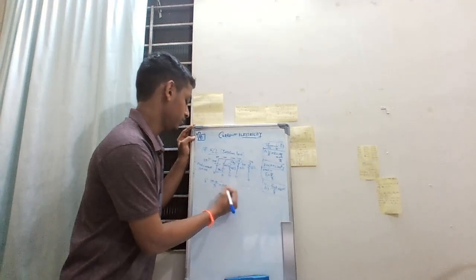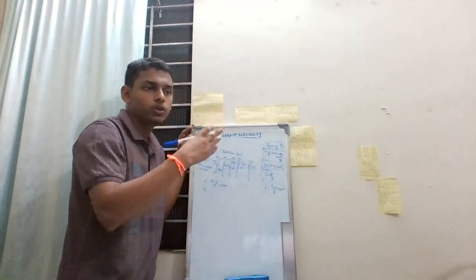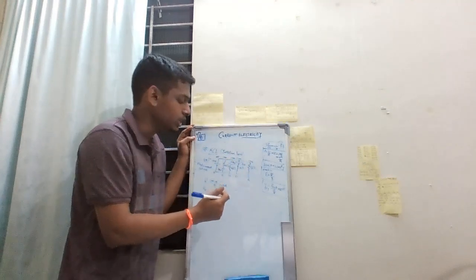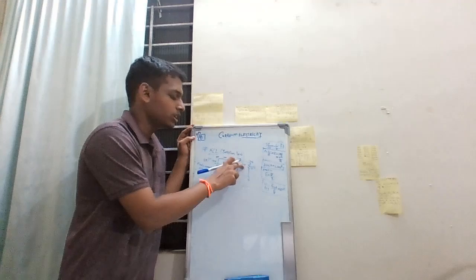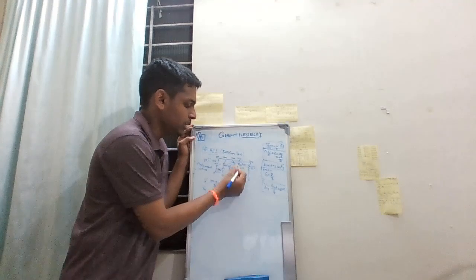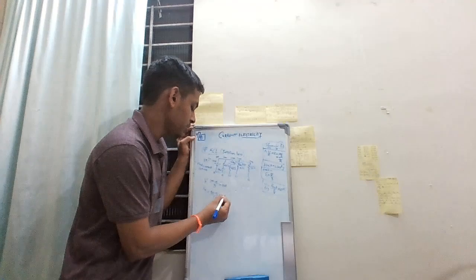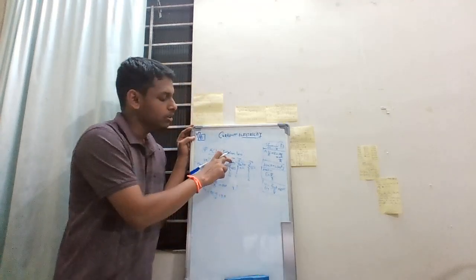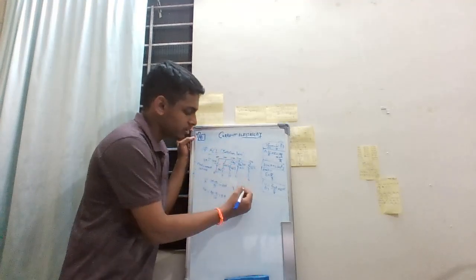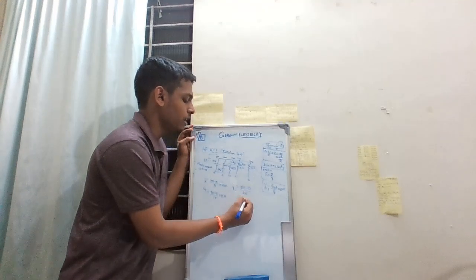20 amperes. For this, we'll use the going above the battery and below the battery. If we come below the battery, potential will decrease by how much potential it already has. 100 minus 20, at this point it would be 80. 80 minus 0 by 10 equals 8 ampere. For I3, the battery is in reverse, so 100 plus 30, so 130 minus 0 divided by 26, 5 ampere.